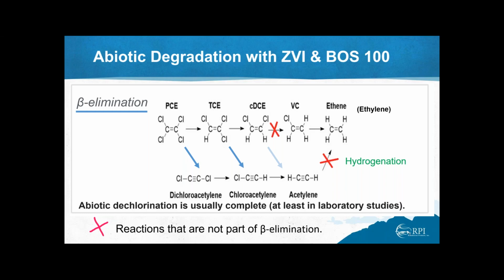The main drawback is that with a ZVI, the iron oxides will tend to corrode. And when that happens, or oxidize, it may prevent further reaction from occurring. As I mentioned earlier, in acidic conditions, corrosion byproducts from water may be soluble, so you can keep your ZVI going a little bit longer. But at pHs above, say, 9 or 10, all depends on the aquifer characteristics, passivation occurs pretty quickly.